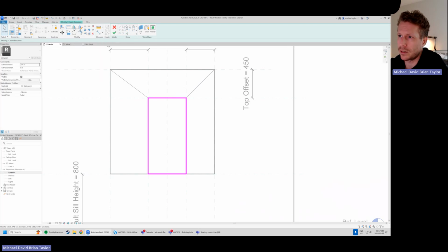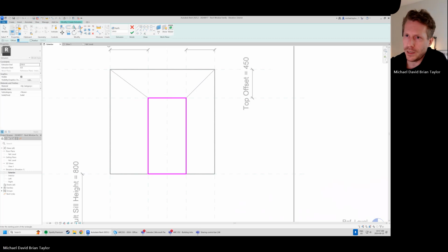So click that rectangle again in our draw panel. Where it says offset, we're going to give it some dimension. These frames are going to range anywhere from, call it 50 millimeters or 2 inches, all the way up to any dimension. You can call it 100 millimeters, maybe 150 millimeters. For us, let's just keep it to 50 for now, and I'll show you what that looks like. So type in 50 up here in our options bar. I'm going to leave that radius unchecked for now, and click our little rectangle tool here.